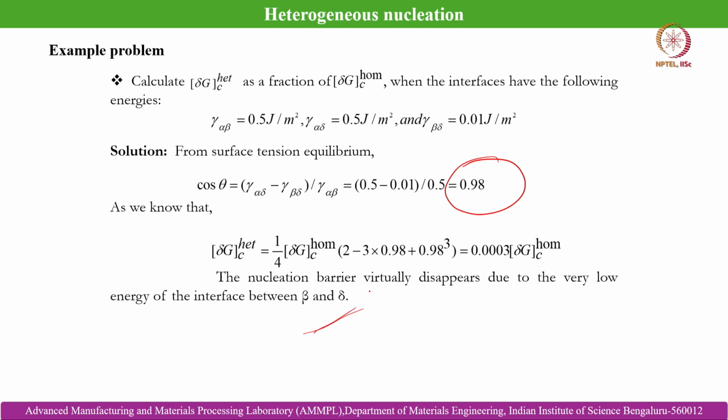So, we should always target towards achieving this. In that way we can decrease the nucleation barrier, and we can achieve a very fine grain microstructure, and that in turn will provide much improved mechanical properties. And also there are many other physical properties of the solidified object which can be impacted by the fine grain microstructure that we can achieve within the solidified objects.